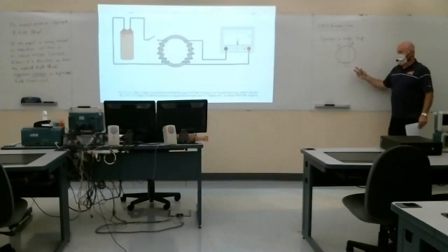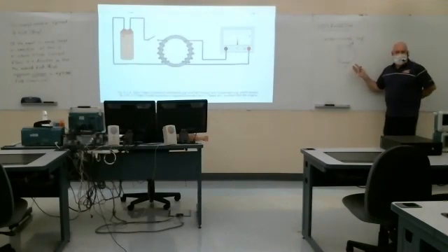But now once I pick that polarity, it's important to pick a current direction that's consistent with that polarity. Again, you have to think of the loop as a voltage source. If I think of the loop as a load with a plus voltage here and a minus voltage here, we'd expect the current to be flowing clockwise through the loop, right? If I view the loop as a load, you have to view it as a generator.